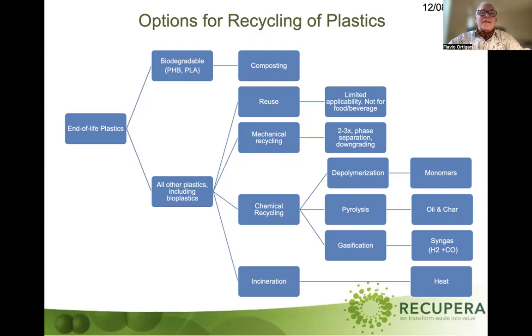That's very clear. Reuse, as I said, is an option, but it's very limited by its applicability, because the plastics will contain those components that you call contaminants or additives, or catalysts, and this is not allowed in certain applications, high quality applications like the food industry, like the biomedical plastics.